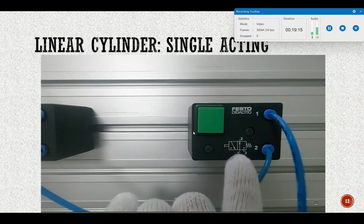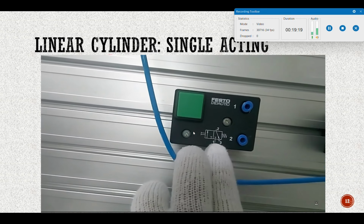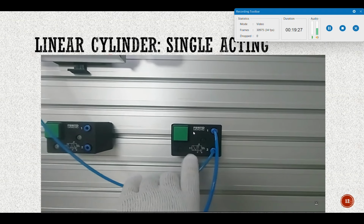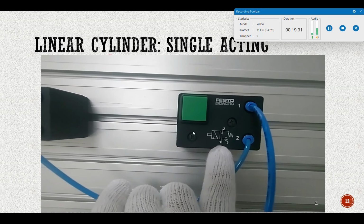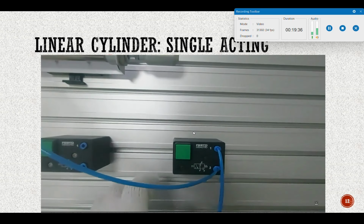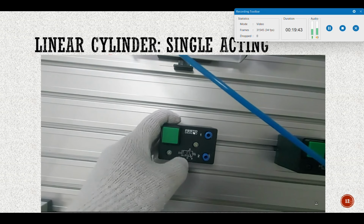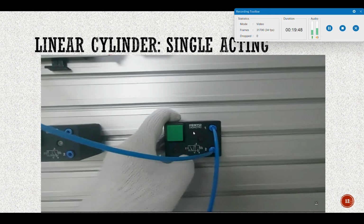Here 1 is directly connected to 2 without any operation. Here you have to operate the valve to make it connected from 1 to 2. So what will happen if you use this valve? This valve has 2 positions and 3 ports, so it is a 3/2 direction control valve with push button. But the difference is, here it is normally open, and this one is normally closed. 1 is not connected to 2, so we say normally closed. And this one is directly connected to 2, so normally open.